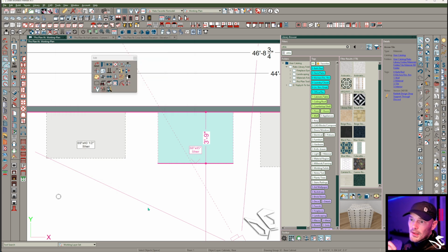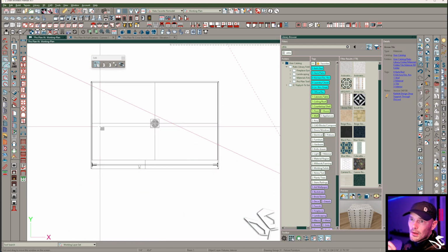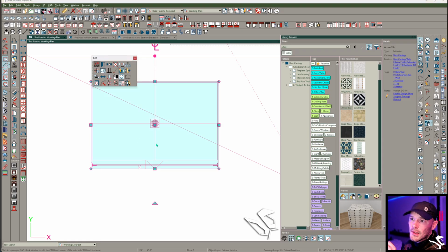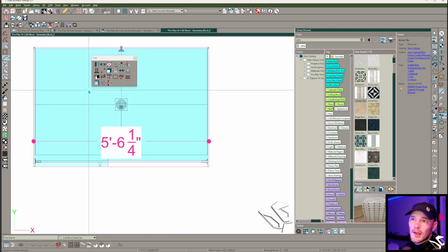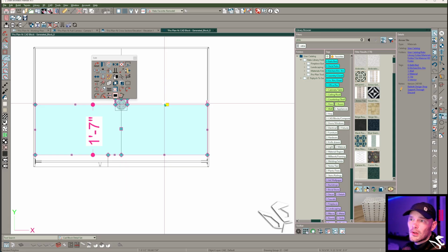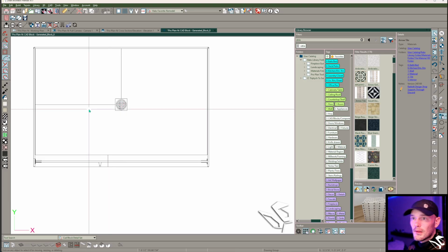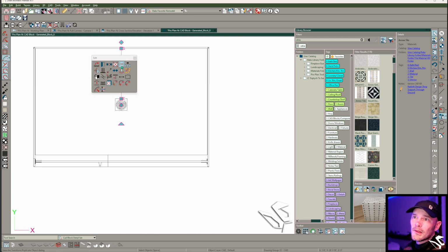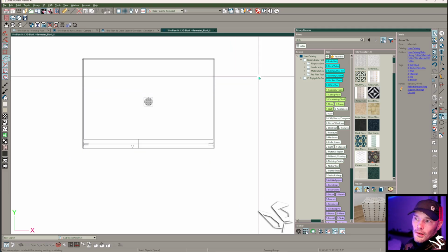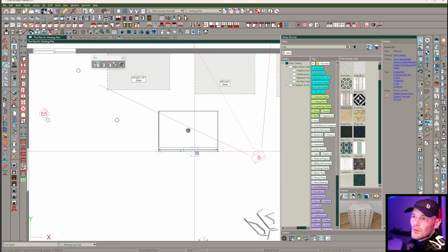And I don't need to show advanced options. And look at what it does. It converts it for me. The only thing that we're showing here is maybe I want to clean up these CAD lines. That means I just get to edit the CAD block, use the line tool, intersected mode. I can just select some things in an intersected mode and get rid of those lines, or say no line on this particular polyline, right? There we go. Last one there, just delete that. There we go. That looks exactly like a shower to me. We can just save that, save this instance of it, and that's how it would look in plan.